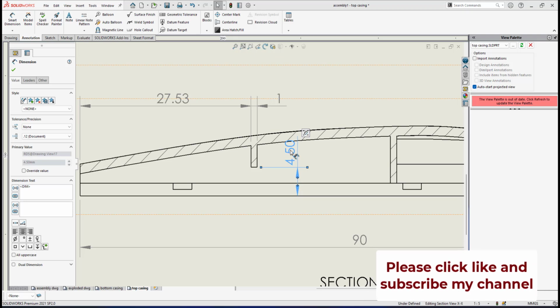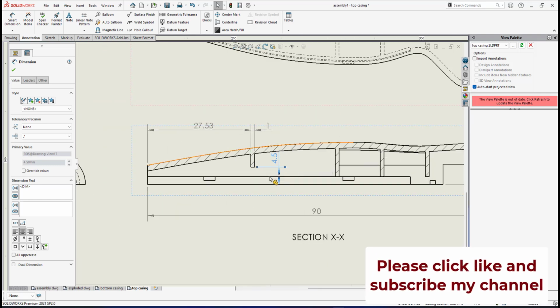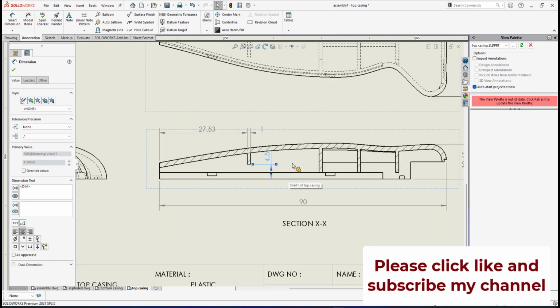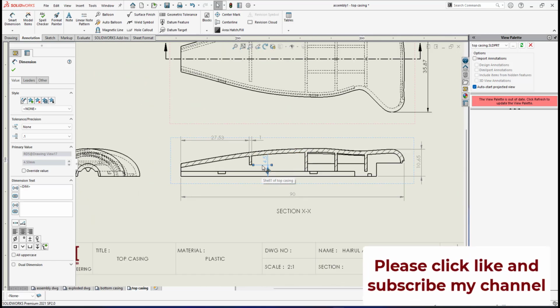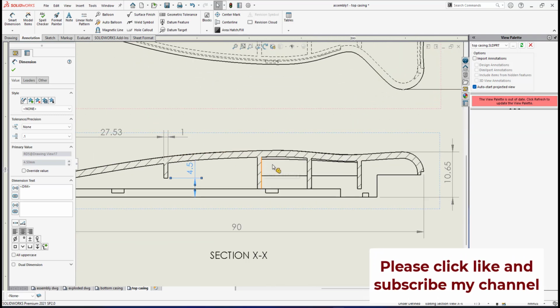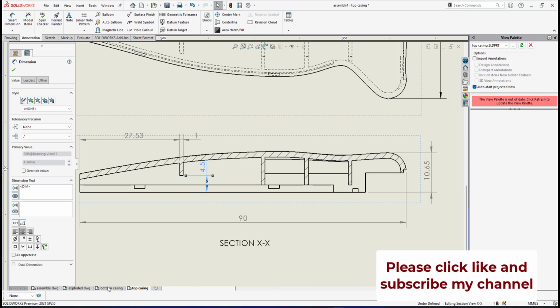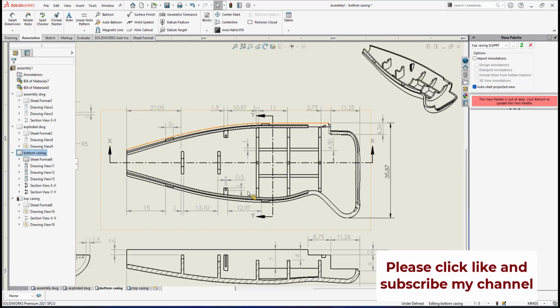Okay, sometimes it is allowed to put dimension beside the object, in terms of clarity, rather than we put it outside, right? Okay, as I explained to you, I don't have to go for this rib. I already explained it from this bottom casing drawing, and the position is aligned with the top casing.